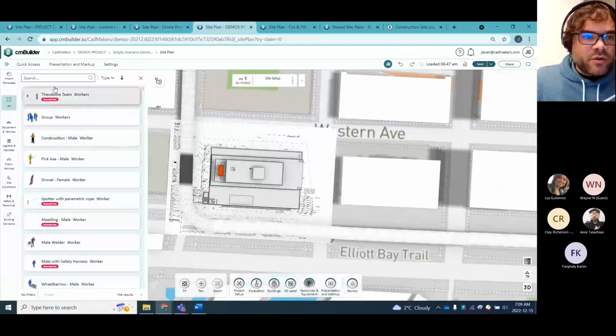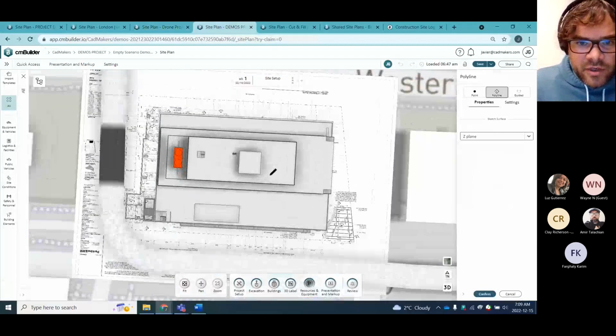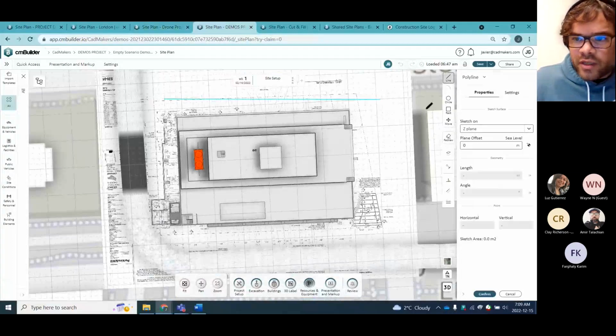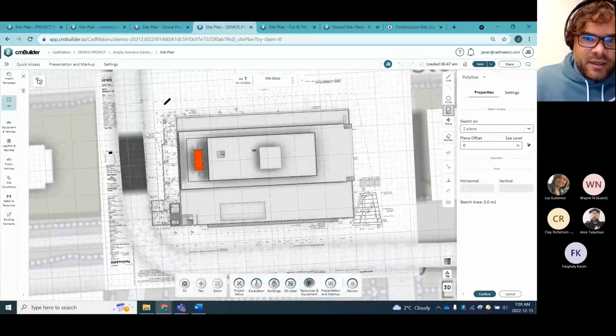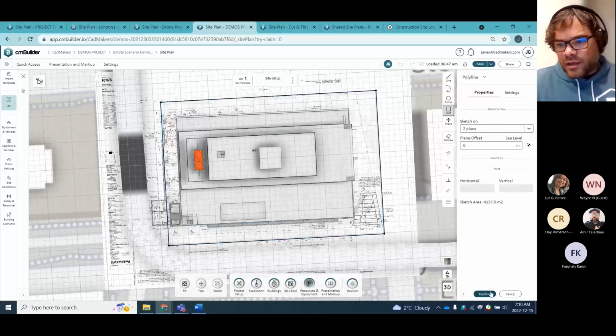So I'm going to go to my resources and equipment, and search the catalog for fencing. Okay, so I'm going to zoom in, and I'm just going to use the drawing as a reference here. Today, I'm going quickly in this demo, so nothing super precise, but you get the idea of the feature function. I have some tools here, sketching tools. In this case I could just sketch out lines, or I'm going to show off our rectangle geometry. You can do circles, arcs, lines, all that kind of stuff.